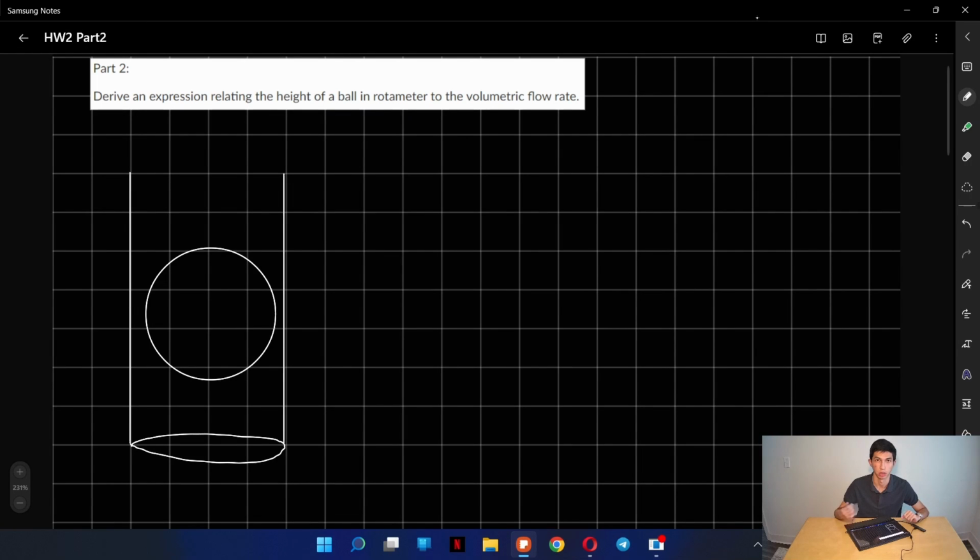Hello everyone, so today in this video we're going to talk about rotameters. It's part 2 of our playlist, and in the question we're asked to find an expression relating the height of a ball in a rotameter to the volumetric flow rate. A rotameter is a type of device which measures the flow rate depending on how high the ball is located. For example, it's usually done with gauges, so the higher the ball, the higher your flow rate is.